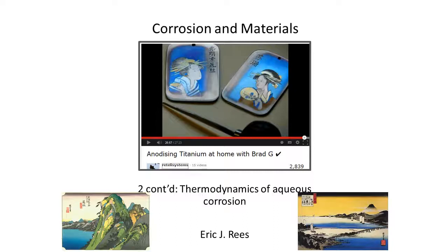Because I told you the passive layer is just 1 to 10 nanometers thick and too thin to see with the eye, you might, if you were empirically minded, have some lingering doubts as to whether I was making up this entire story about the passive layer. These nice titanium art pictures show you that I was indeed telling the truth. Around the edge, this is normal titanium, which is just silvery, as you expect, because the passive oxide is too thin to see.